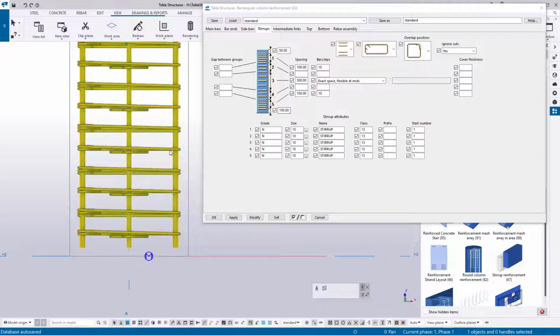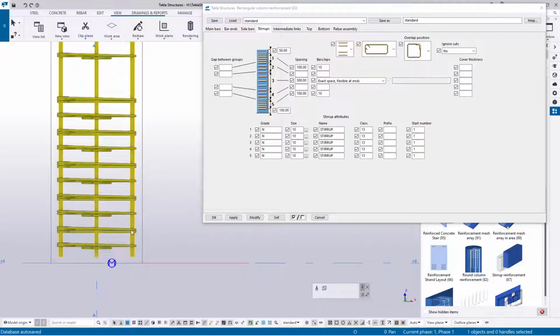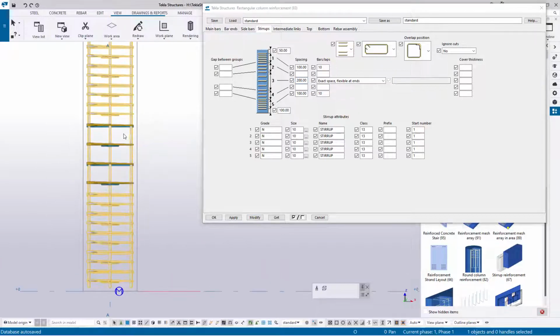It works well. Now, in terms of our lap length, we've got 100 millimeter, and we've got 300, and we've got 100 again. So this is not right. What the engineer wants is a 200 main spacing. Modify. That will change that middle field. And for the bottom, it should be half of the main, and that's 100. That's correct. And because this is number of bars, because we have a meter, we need 10 bars at 100.